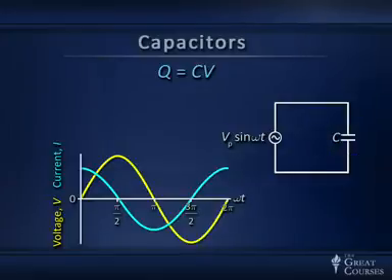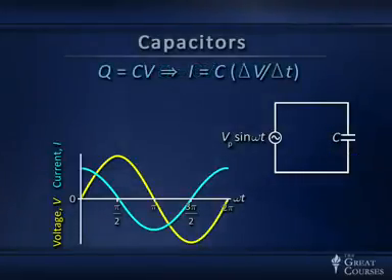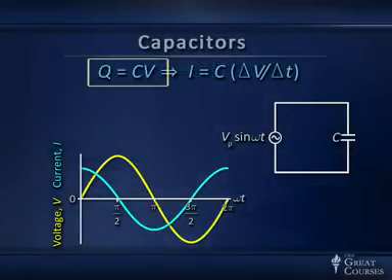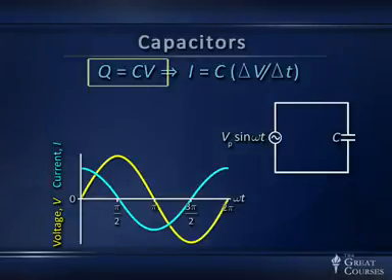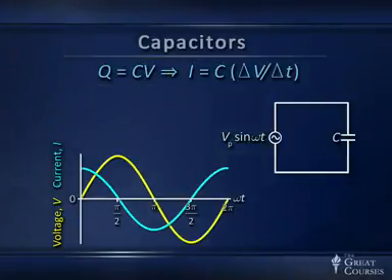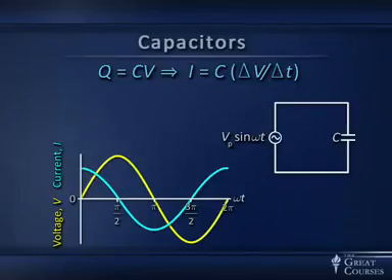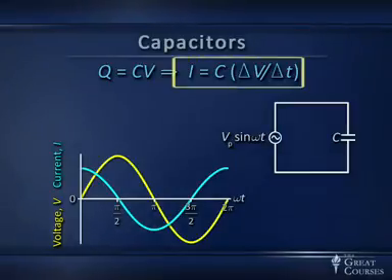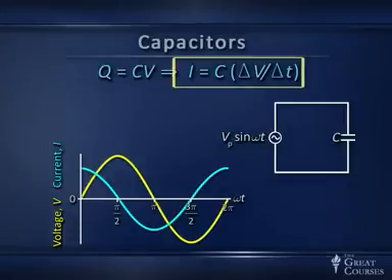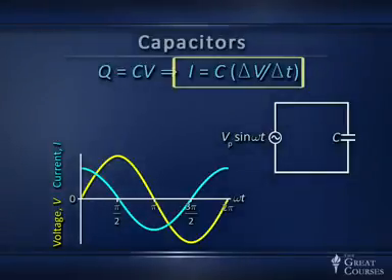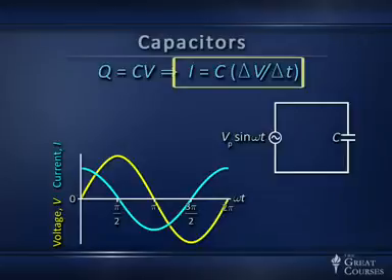If I take the rate of change of that equation, take the rate of change of the left side, rate of change of charge on the capacitor. Well, where's the charge come from? It comes flowing along the wires coming into the capacitor. It's carried by the currents. And so the rate of change on the capacitor plates, rate of change of charge, is the rate at which charge is flowing through those wires, and that's simply called current. So if I take the rate of change of this equation at the top describing a capacitor, I have I, that is delta Q over delta T, is C delta V over delta T.